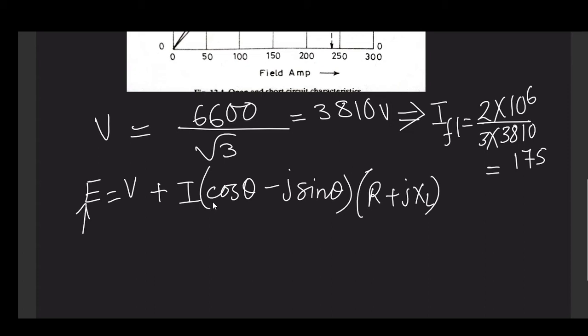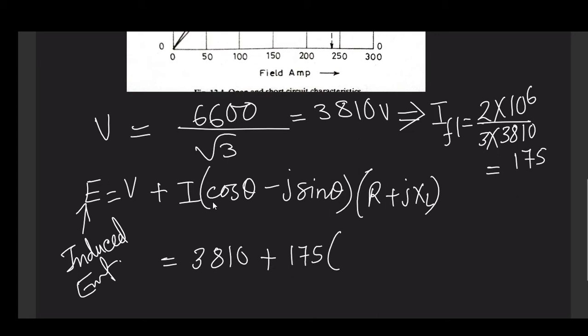So now it is our induced EMF, not open circuit EMF, induced EMF. So what we are getting here is something like 381 angle 0 plus 175 with power factor as usual 0.8, so 0.8 minus j0.6, and this one is like 0.1 plus j2.